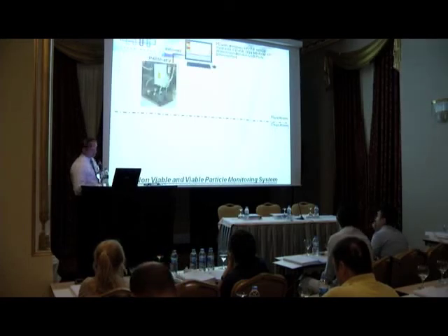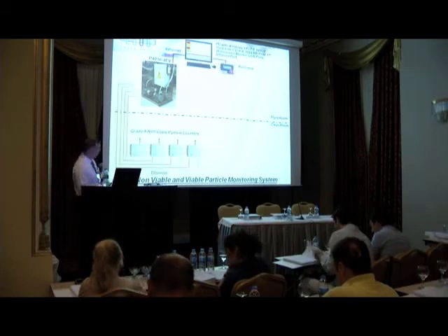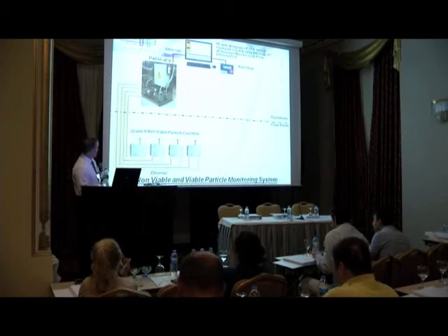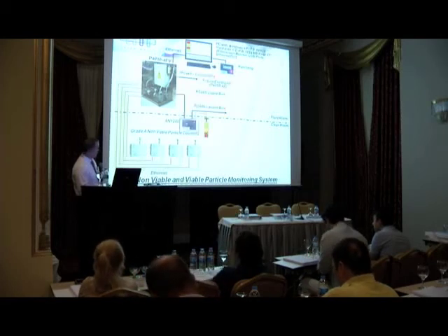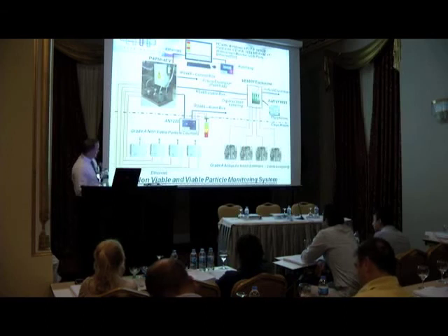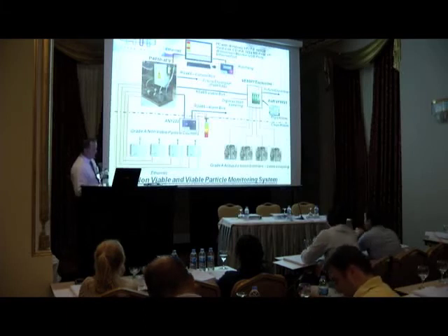So what we're going to do now is, we've looked at some simple system topologies. All we're doing here really is showing the same thing again. You've got your computer, your control unit, your watchdog, your non-viable particle counters, their alarm annunciation, and now we're entering into the equation your viable counters, and this little device here, which is a module that does all the clever stuff with measuring the flow. It also detects when you've got a plate fitted to your sampler as well.